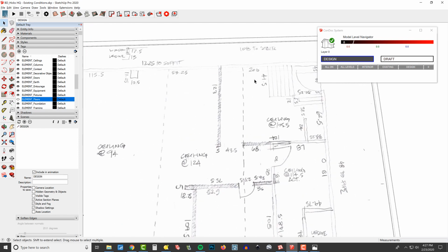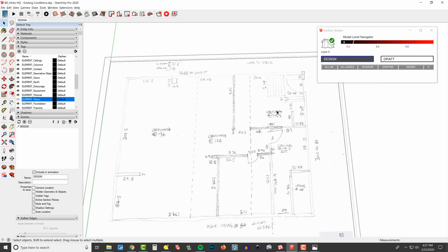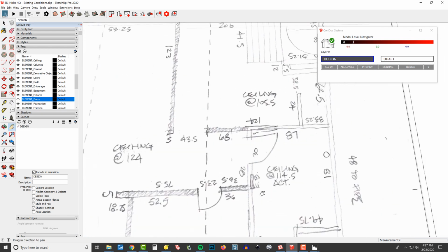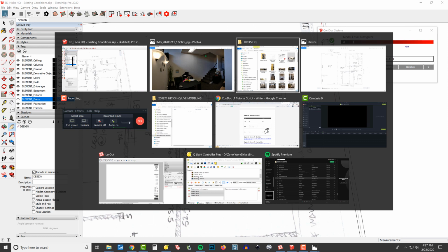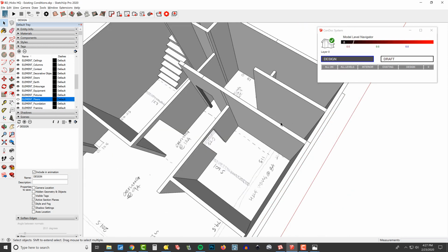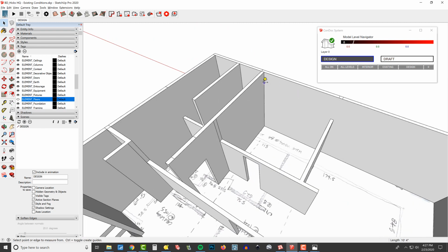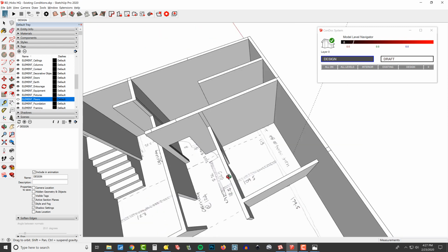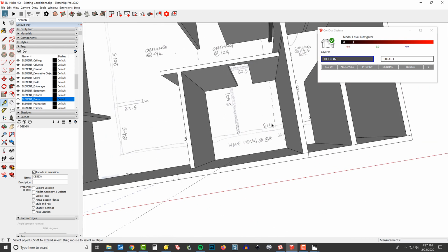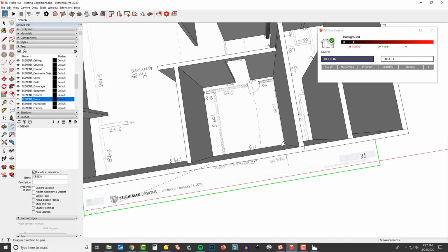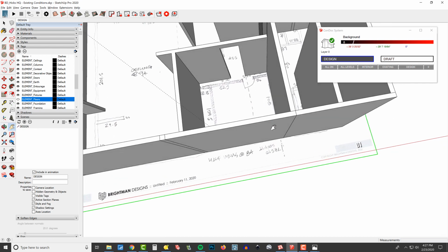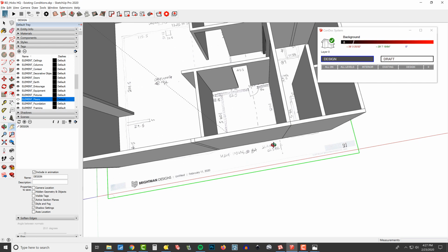So to resolve this, the ceiling is at 105.5. I'm getting that right here, and then it is 73.5 inches off this back wall is our soffit. So let's consider drawing that 73.5 off that back wall. Like that. And let's scoot our field notes again. So there's our back wall, kind of like that. So 73.5. And this is where the soffit jumps up.